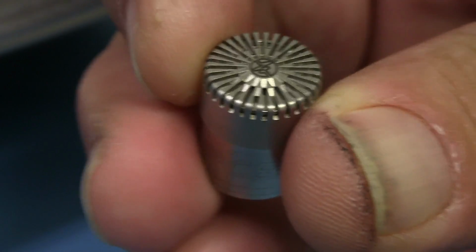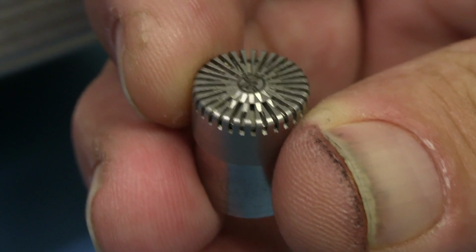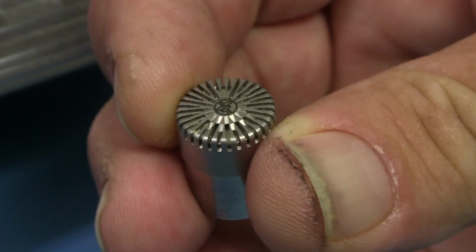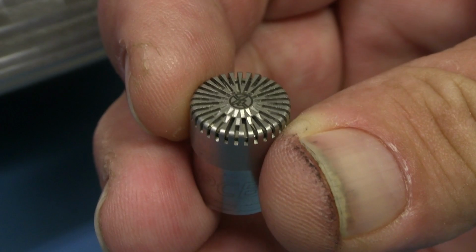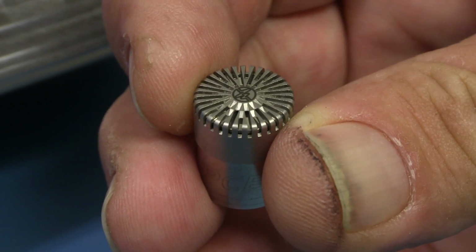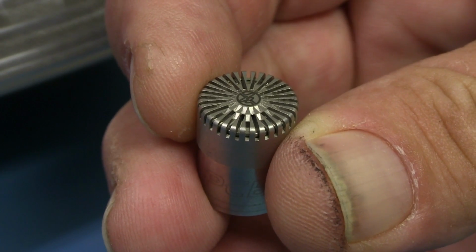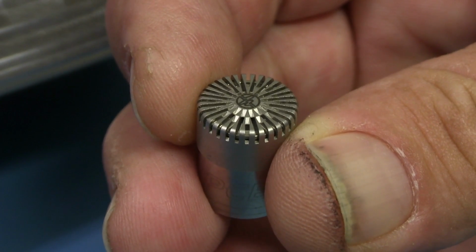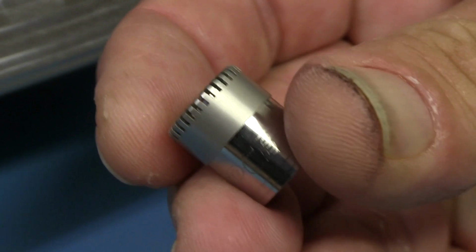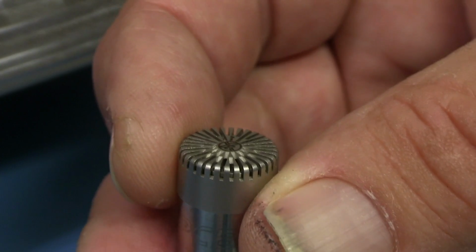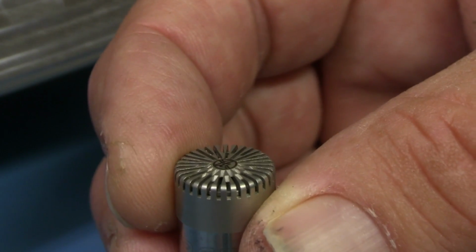Basically, it needs protection for the diaphragm, yet acoustic transparency so that the sound gets to it. Of course. And with a large number of relatively small openings like that, we get better than 50% opening ratio, and it will accept sound from pretty much any angle. So it behaves pretty much like a bare diaphragm, just with a bit of protection.